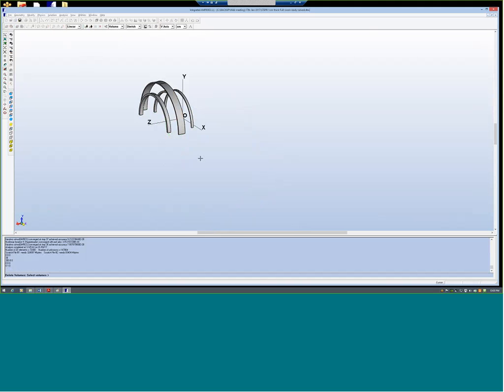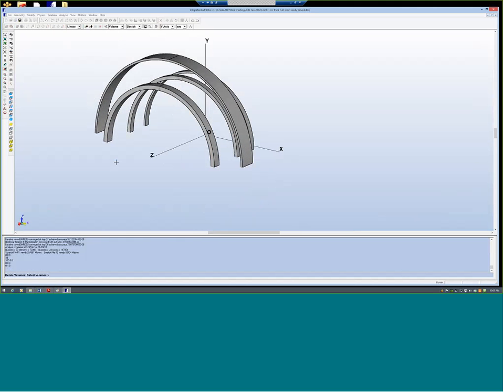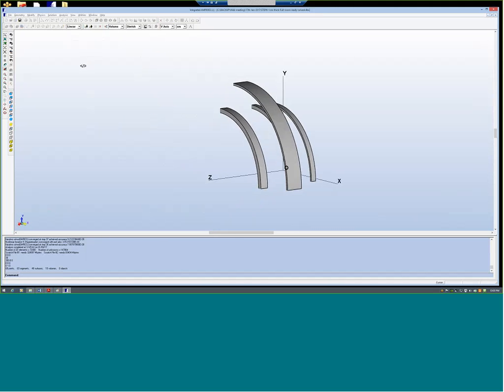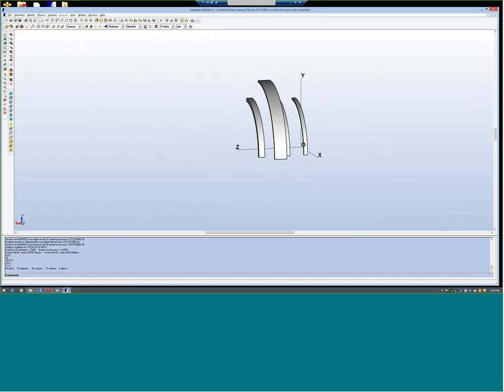Okay. Gone. Next, I want to apply one more, because if you see x is equal to 0 plane also, that is the yz plane, again you got an anti-symmetry. Then we will use that anti-symmetry facility, then delete volume. So your model has to be x greater than or equal to 0. So that's why these parts have to be deleted. Done. So now you got only 1/8 of the model.